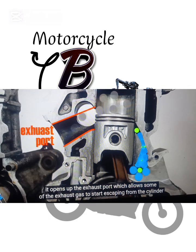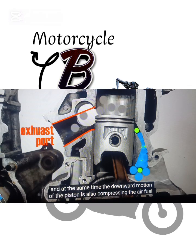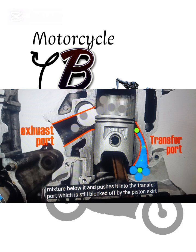Now as the piston is going down, it opens up the exhaust port, which allows some of the exhaust gas to start escaping from the cylinder, and at the same time, the downward motion of the piston is also compressing the air-fuel mixture below it and pushes it into the transfer port, which is still blocked off by the piston skirt.